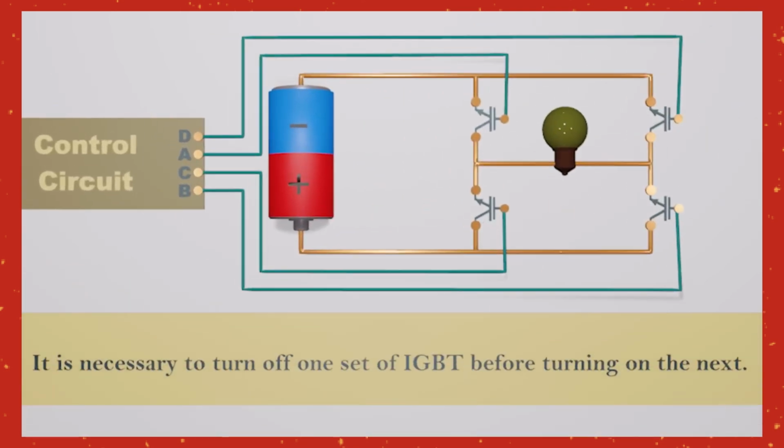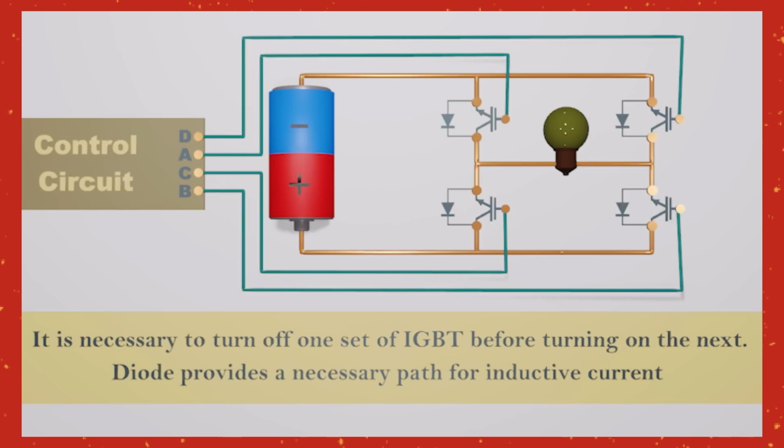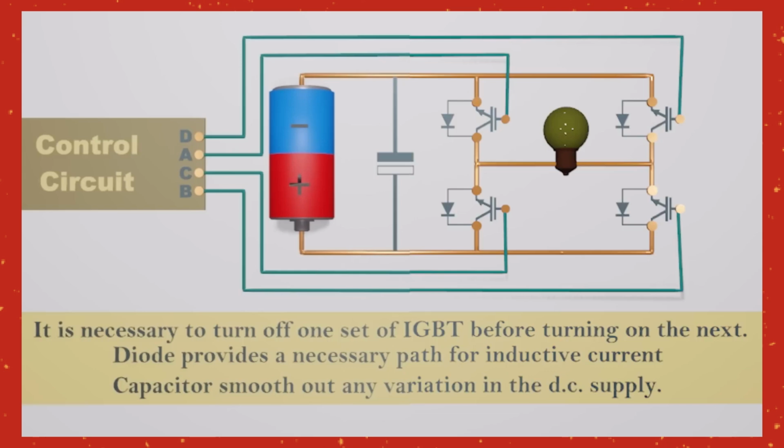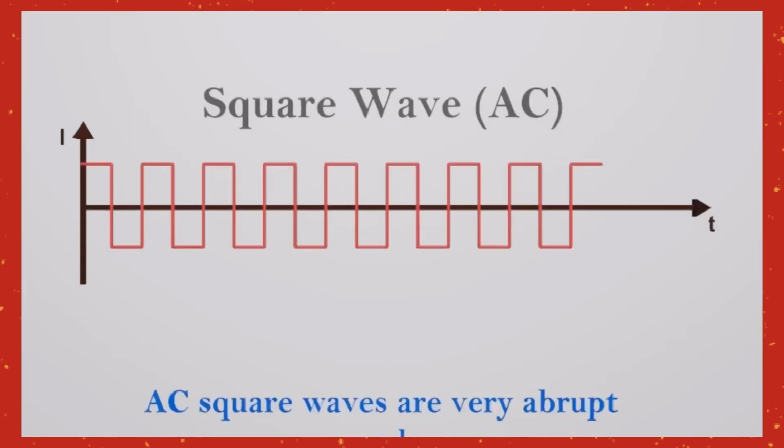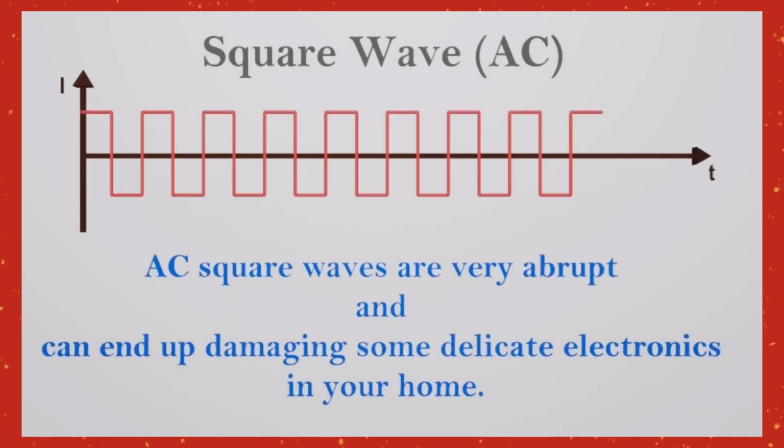In a modified square wave design as shown above, the square waveform shape basically remains the same, but the size of each section of the waveform is appropriately dimensioned so that its average value matches closely to an AC waveform's average value. As you can see, there's a proportionate amount of gap or null areas between each square block. These further developments in the industry allowed for the creation of rectification circuits, giving way to the creation of pure sine waves.